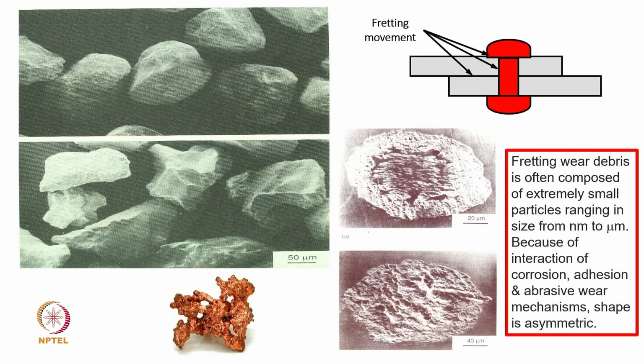Now, this is another interesting thing. We say that in 3 body abrasion, we mentioned that the particle sizes are much smaller, and quite possibly even the very sharp, irregular shape particles are getting rounded. So, I should be happy if the number of particles at any stage is many, but the size is almost negligible. I can be very happy from that angle, and say this is a good thing. However, I may be unhappy also to some extent.